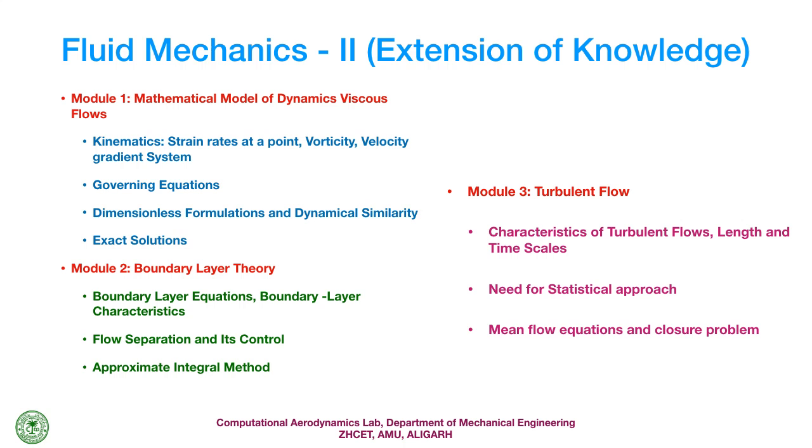These mean flow equations are called Reynolds averaged Navier-Stokes equations, and this averaging procedure creates certain additional terms which need to be modeled. This is called the closure problem, because you do not have an equation directly available for those terms.